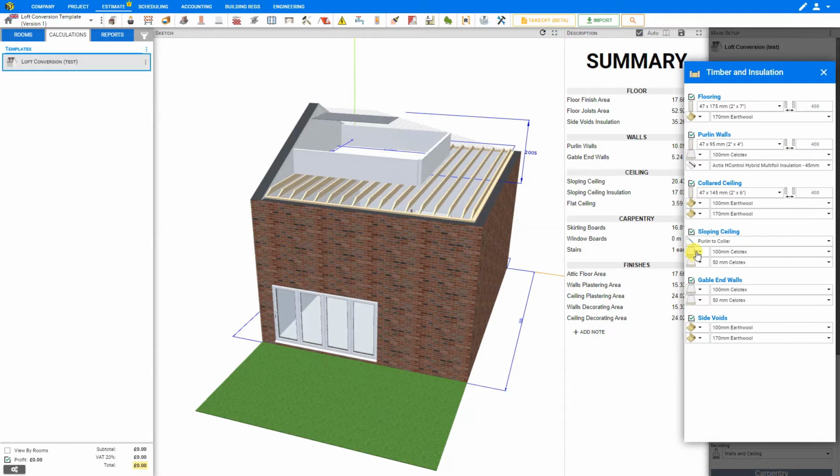And for the insulation type that you choose, this would usually depend on the thickness of the rafters. If there's a non-breathing membrane, then generally you have to provide a 50 millimeter air gap. So if you're not sure, take a look at your building regulation U-value calculation to figure out what insulation you require. For this example, we'll leave them at a combined default of 150 millimeters.